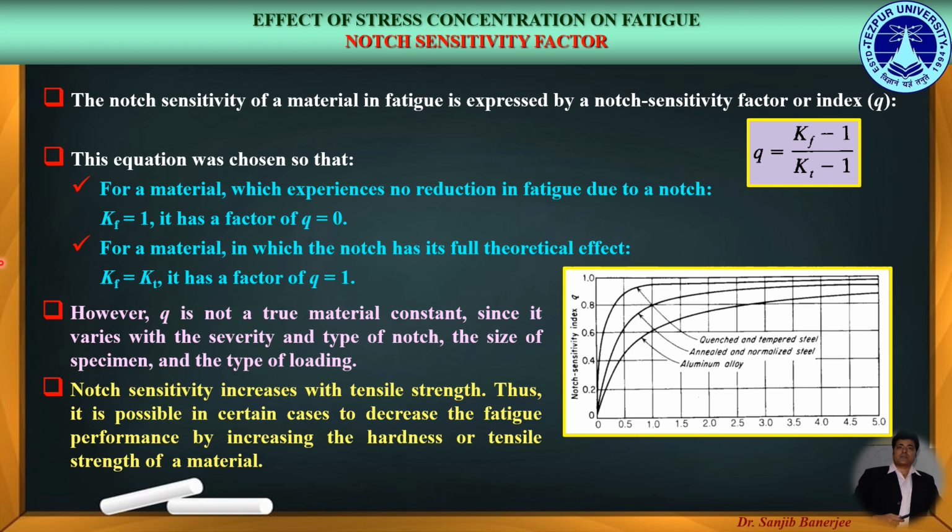Now, the value of Q is not a true material constant because it varies with the severity and type of the notch, the size of the specimen, and the type of loading.